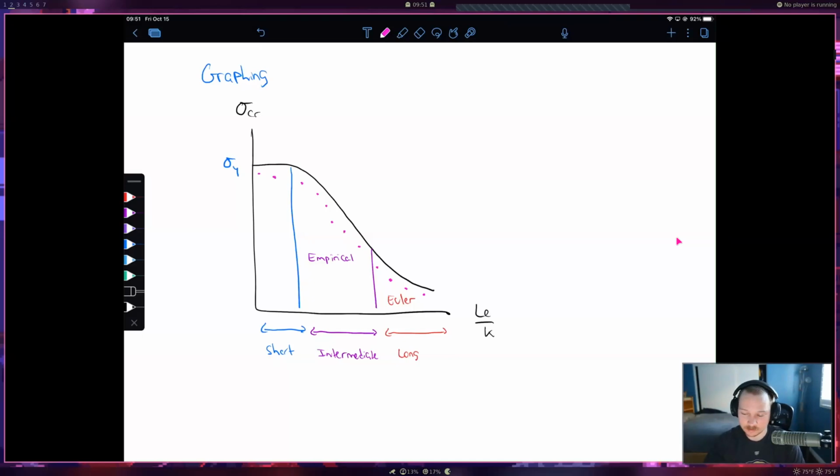This is another source of error. I guess I'll just tell you now. Unless it's been upgraded, because I know the lab technician Don has been talking about upgrading the end supports to a more sturdy material. The end supports in the past few semesters have been kind of weak. I don't know what they're made out of, but the fixed support especially gets damaged. There's a little nub for the fixed support, and in the past it's been easily damaged where it gets kind of bent. So if it's bent, you already have a crooked column, and that's going to affect the readings you have in the lab. So the experimental curve is most likely not going to look as pretty as this does here, but it should be similar. Hopefully. We'll see though, right?